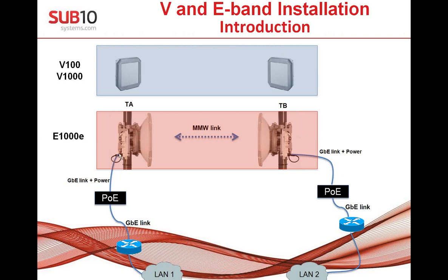And 100 meters can be from the terminal to the PoE and also from the PoE to the gigabit switch. It means these two blue connections, if you zoom in on the length, you cannot go over 100 meters. If you say, okay, I will put 100 meters here and 50 meters here, it will not work. Keep in mind, the gigabit limit is 100 meters, and PoE is not a gigabit device. It's just passing or adding power, and you have to calculate 100 meters from your switch or from the indoor device going to the PoE, and then add the cable length from the PoE to the terminal.